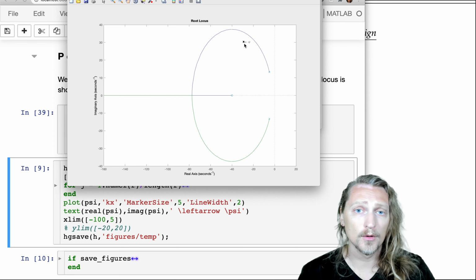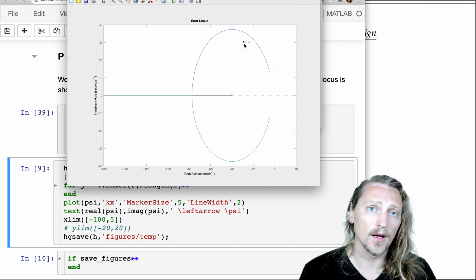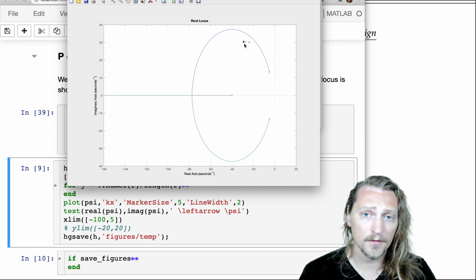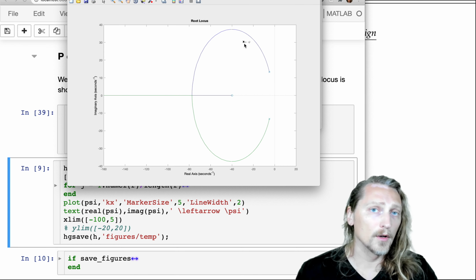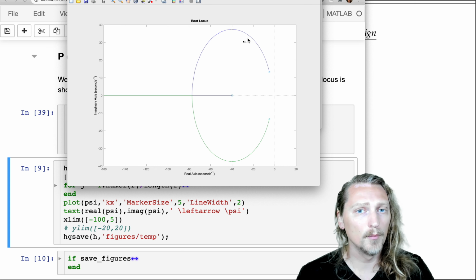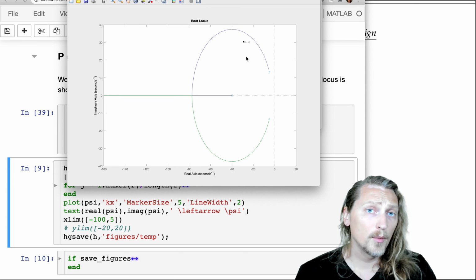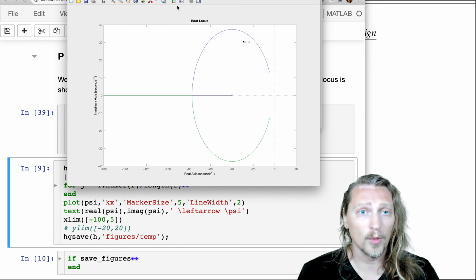At least using the methods that we're using, if you're going to move the root locus itself, the way to do that is to use a derivative compensator or a lead compensator if you so choose. So we're going to need to move this root locus. But we can use a proportional controller to get as close as we can to this point.